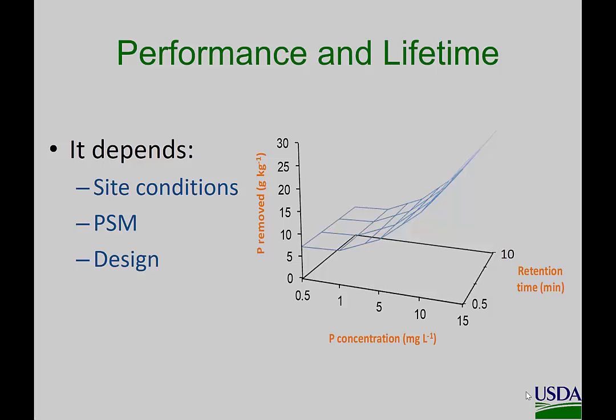It depends on the site conditions. What kind of flow rates do you have? What kind of total flow volumes do you have? What's your phosphorus concentration at the site? How much material did you use? How was it designed? What's the retention time for your structure? All these things are very important in dictating how to design it and how it will perform.